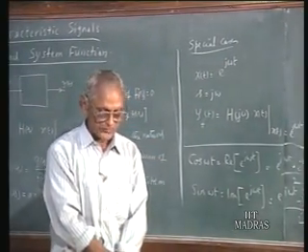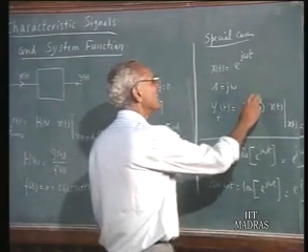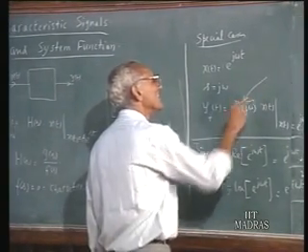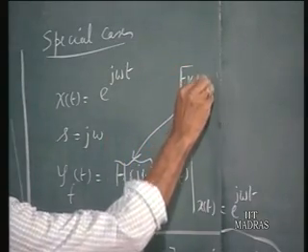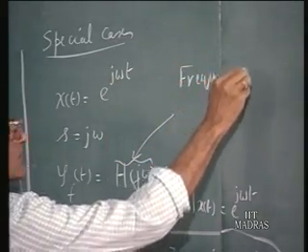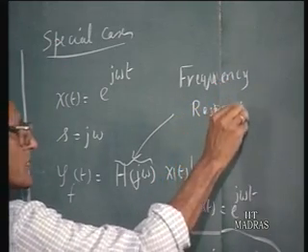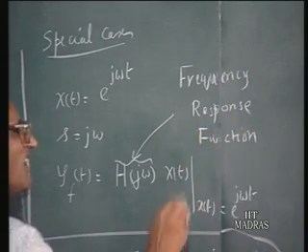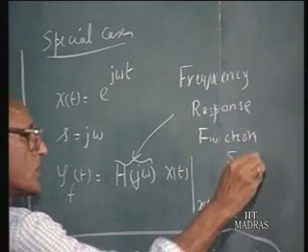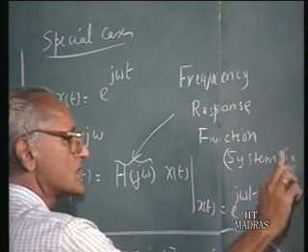So this is also important, and when we study Fourier transform methods and Fourier series methods later on, H of j omega becomes very important. This H of j omega is itself sometimes called the system function, but more commonly we call it the frequency response function. Also, sometimes when there is no scope for confusion, this is also called the system function.